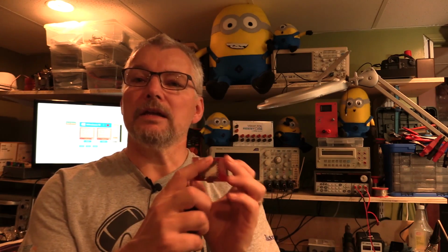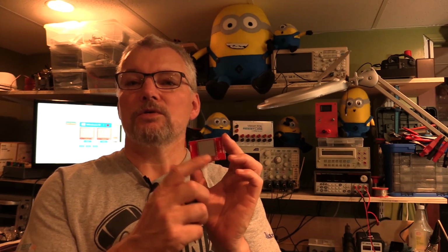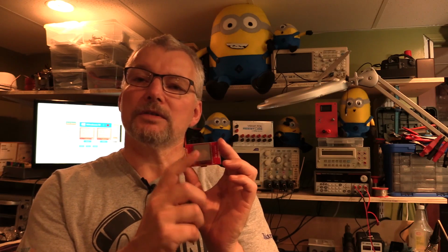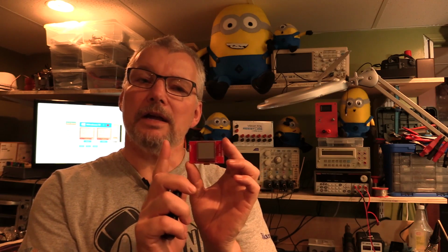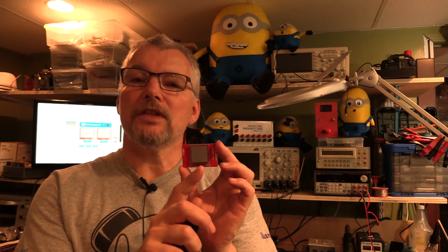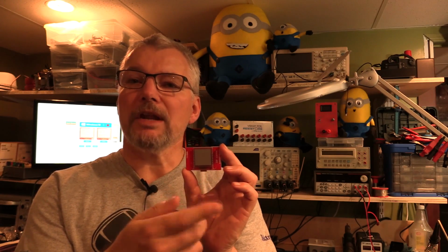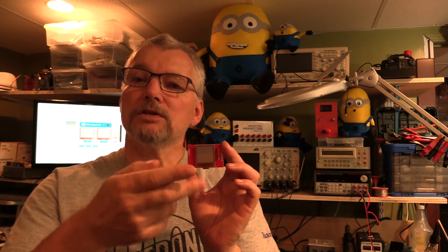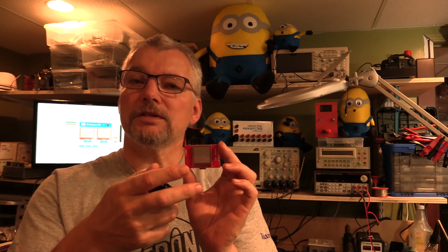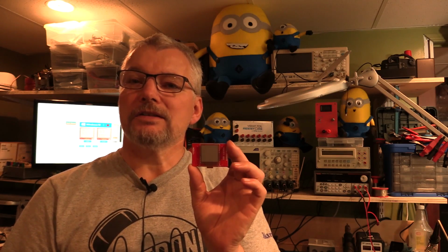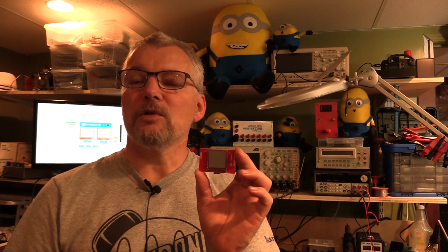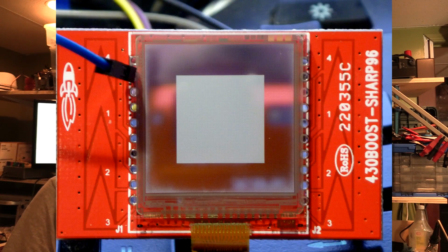And one of the key things is that they can actually build up a bias voltage, like a static almost, on the display. So if you put an image on here and you leave it there for a long time, maybe an hour or 2, without alternating the bias voltage on the display, it can actually stick there. It's a little bit like the old CRT monitors and things, where if you left the same image, it would burn an image on it.